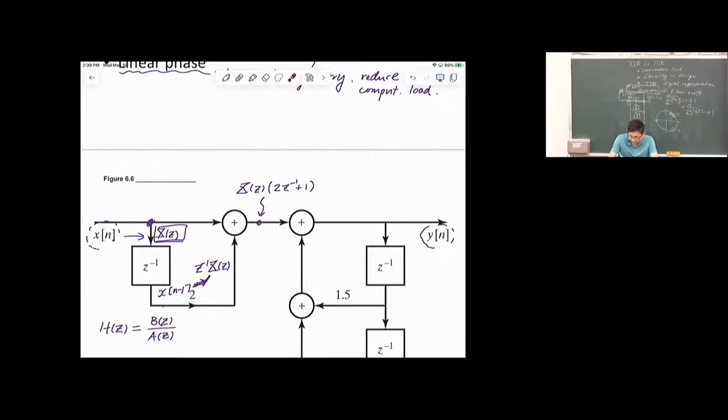The inverse is one sample of delay, okay? Imagine you can hold the signal by one sample and let it show up one sample later. So this is a delay component. The output is simply the input you receive delayed by one sample right here.